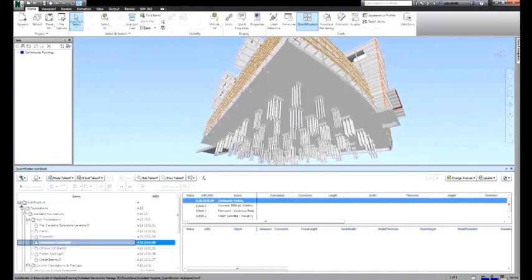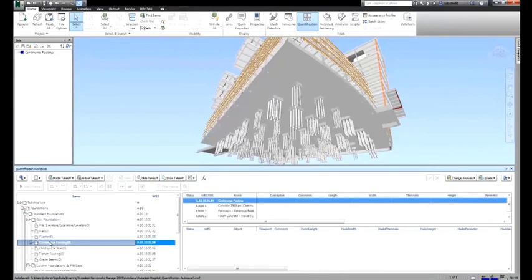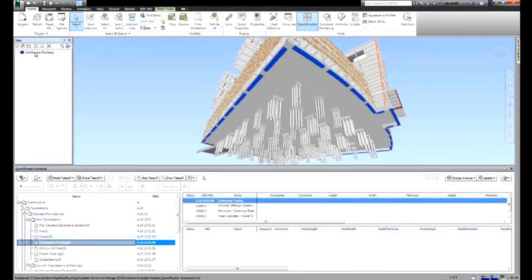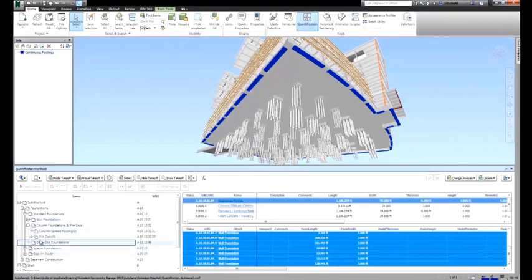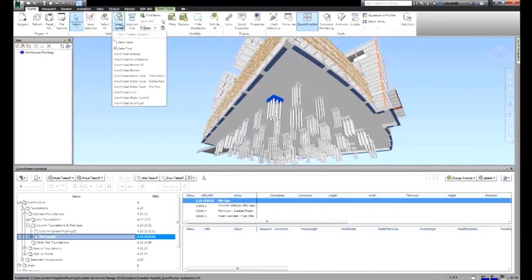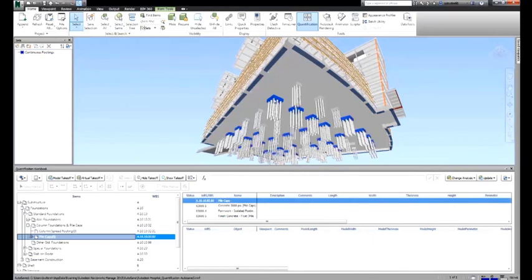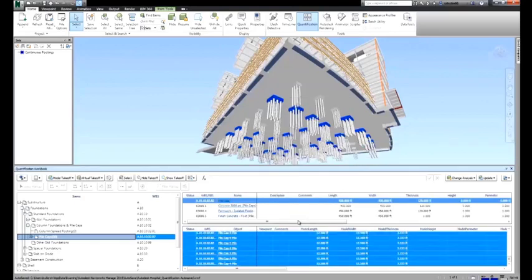Here we're seeing item and resource catalog information used to classify model elements further than the model ordering tools can. When the catalog is available, it is possible to quantify the model using intuitive tools in Navisworks. Simply select an appropriate item within the catalog for quantification, then drag and drop the elements from the model to the appropriate items. The workbook also leverages the item breakdown structures and the resource breakdown structures, and in that we can see a roll-up of the total quantities of an item collection with its resources.